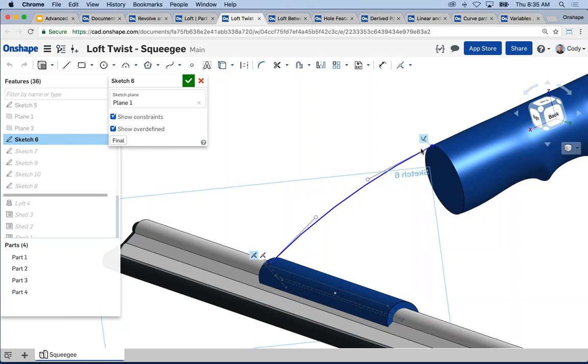Make sure that your guide is attached to your loft profile in some way, either using Pierce or coincident, right? So essentially the same rule as the sweep command. When you're attaching your profile to your path, you must attach your guide to your profile in some way. And if your loft has many profiles, the same rule applies for points along your guide.